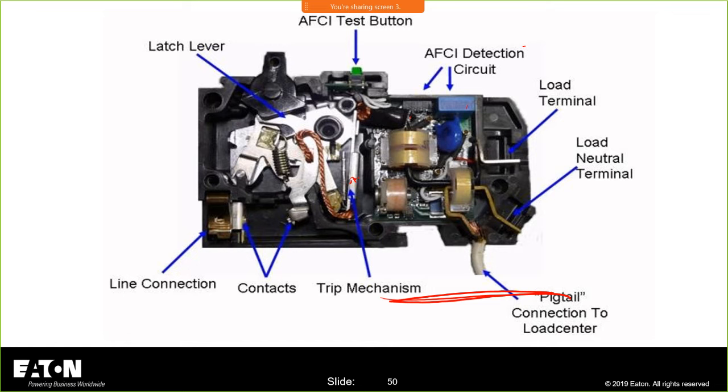Now, the other thing to remember when you wire these in, you better land that pigtail. It's just like a GFCI. If you don't land the pigtail, you've got a very expensive thermomagnetic circuit breaker. So you've got to land that pigtail.